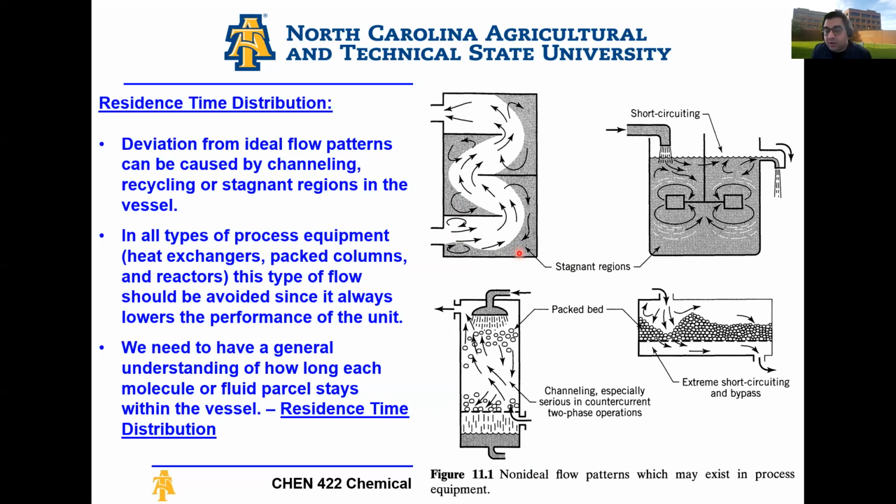It's just there, and it's a non-ideality. It's just a non-ideality you need to account for, and this is actually very common. And the second thing you can see here is you see this a lot when you have impellers as well. So there's a mixer, and as you can see, if I'm introducing the feed from the top of my CSTR, the mixer is not going to allow the feed to react with what's happening at the bottom, right? It's just short-circuiting it to the output.